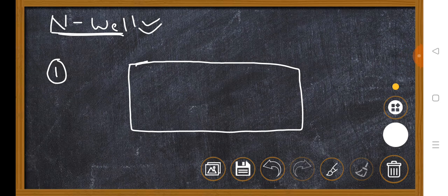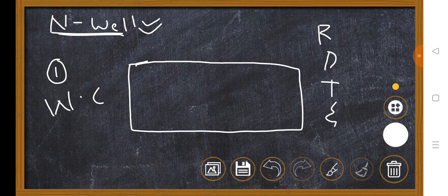What is the first step in any fabrication process? Absolutely, wafer creation. Now I have considered a wafer. I already said that you have to talk about three parameters: resistivity, diameter, thickness, and don't forget doping. Is it clear? Now tell me, if you are doing the N-well fabrication process, what should the substrate be? Absolutely, a P-type substrate. I hope you are clear.